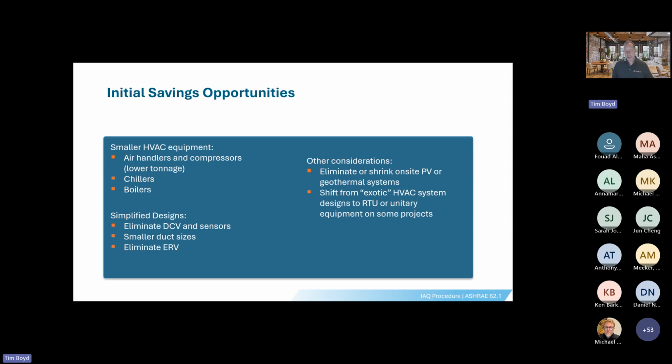There is also, under the 90.1 code, and I didn't go into this or show it, the ERV requirement. If you read the ERV table, what you'll notice is you can get below that ERV strategy and not require an ERV if the outdoor air is below a certain percentage of the supply air you're supplying to that space. And it graduates as you go up in scale, as you know.